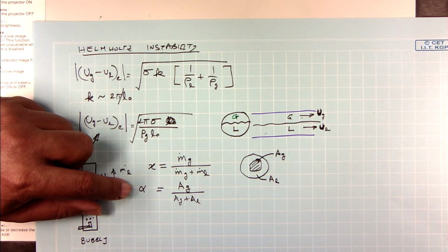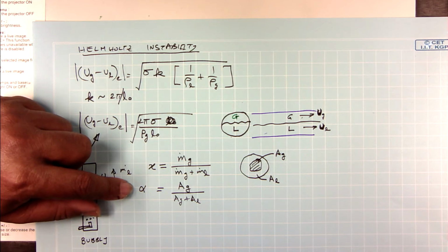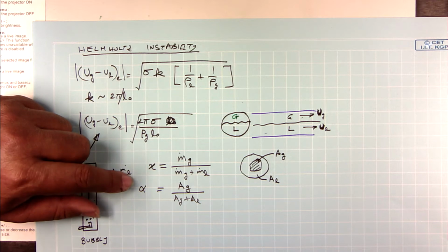Okay, and typically this measurement can be done by using things like X-ray tomography. So you illuminate it with X-ray and you can very clearly visualize how much is gas and how much is liquid. But X-ray tomography is a very specialized measurement technique and it is very expensive also. So not all commercial operations will have the luxury of doing an X-ray type of measurement.